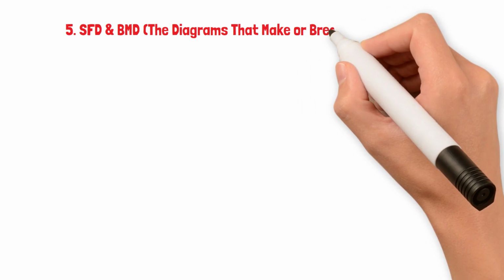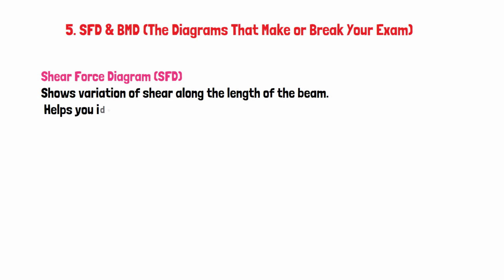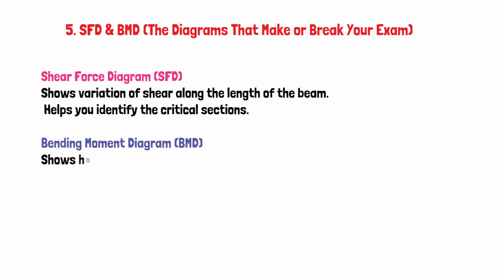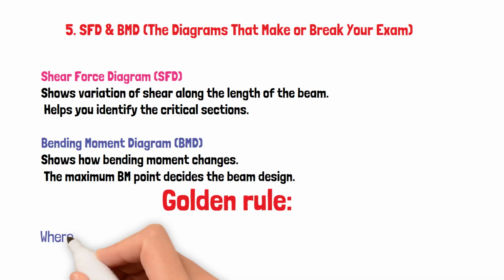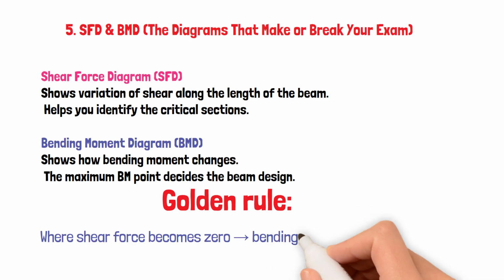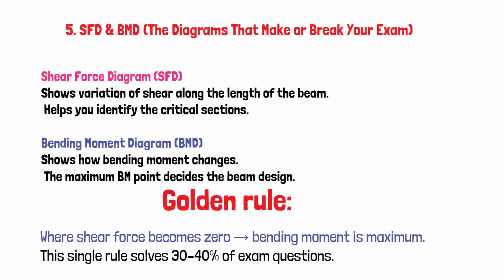5. SFD and BMD, the diagrams that make or break your exam. Shear force diagram, SFD, shows variation of shear along the length of the beam, helps you identify the critical sections. Bending moment diagram, BMD, shows how bending moment changes. The maximum BM point decides the beam design. Golden rule: where shear force becomes 0, bending moment is maximum. This single rule solves 30 to 40% of exam questions.